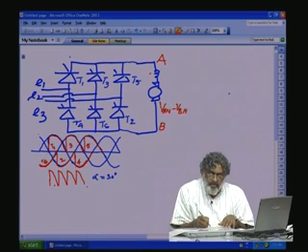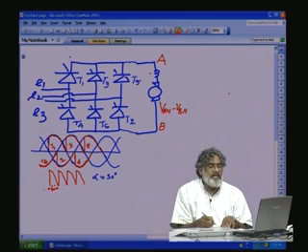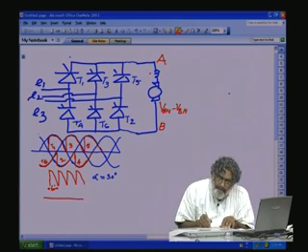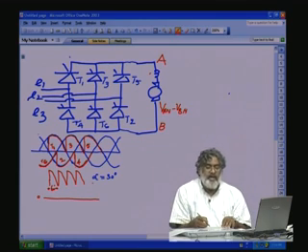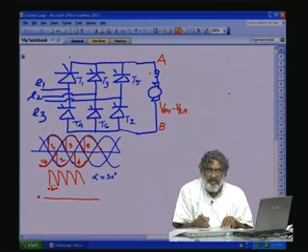So, this will go in a cycle. So, this is 60-degree duration. So, we have the ripple will be 6 times the fundamental. This is the 0. Okay. Now, as the firing angle varies, so this will have an average DC voltage.